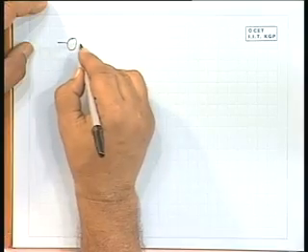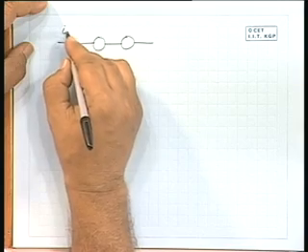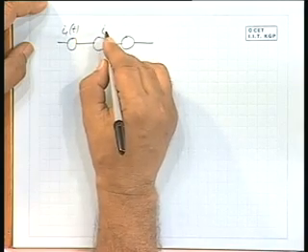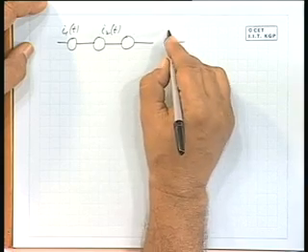Like the voltage sources, the current sources cannot be put in series unless they are all identical. That is, current sources, if you want to put them in series, all of them must have the same current rating. So, I1T, I2T and so on, INT.